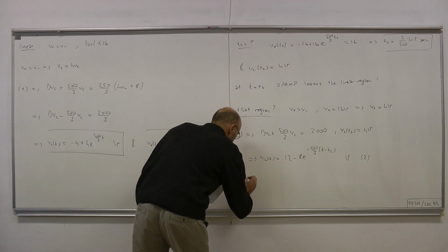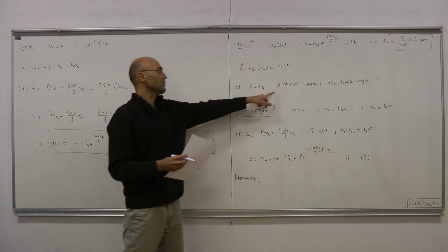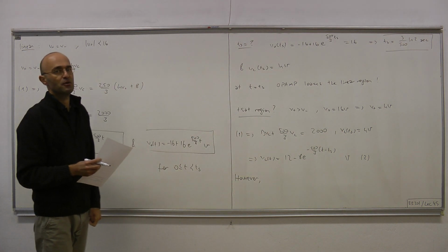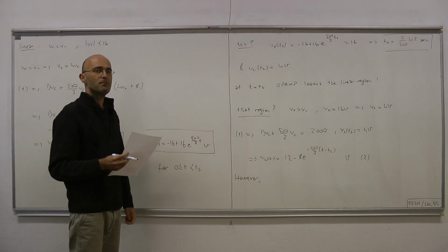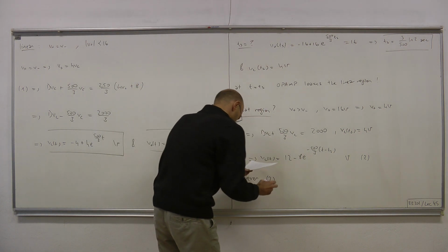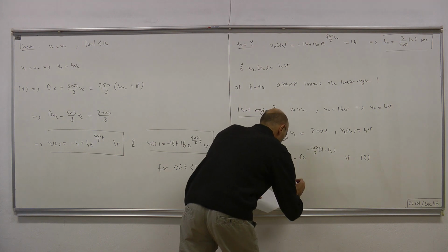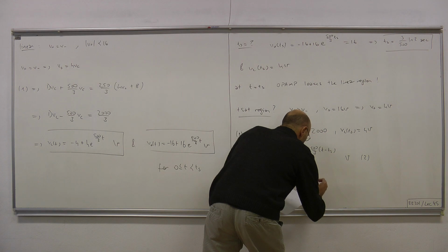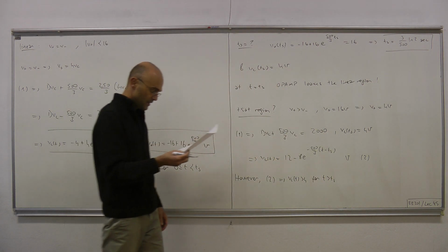So we have to go somewhere else. We are kicked out of the linear region, and it turned out that we cannot remain in the positive saturation region. So therefore there's only one place left that we can go, that's the negative saturation region. Okay. 2 implies we see T greater than 4 for T greater than saturation time, TS.